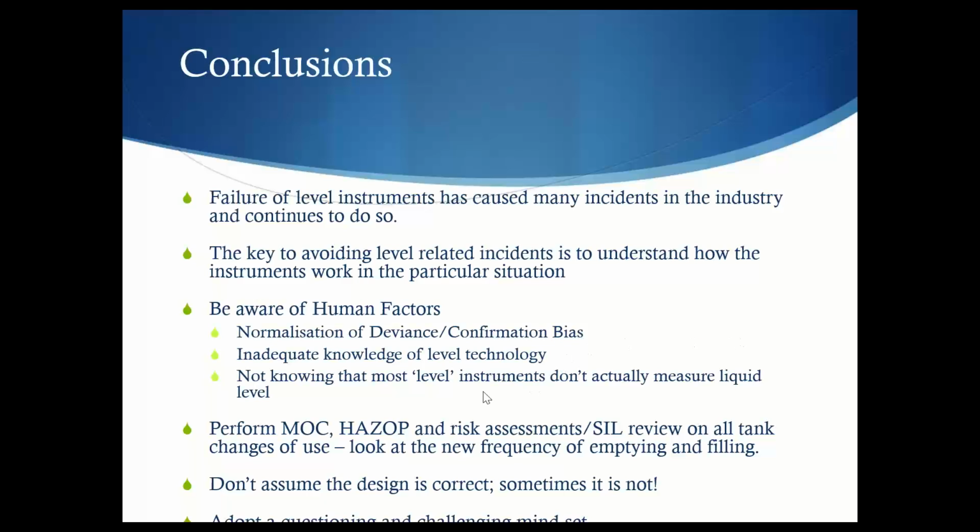Make sure you know what technology you've got. Most level instruments don't actually measure level, so know what indications you need to be looking for. Perform your management of change on your tanks if you're changing the service. Look at how often you're opening them and filling them, and don't assume that the design is correct, because sometimes it's not. So that challenging mindset you need all the time.